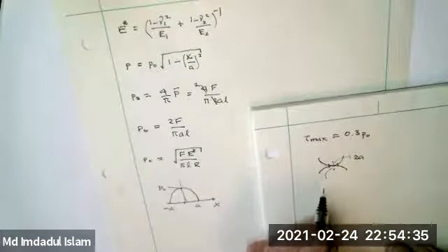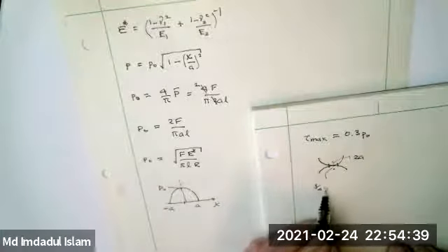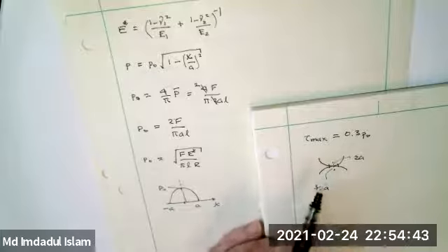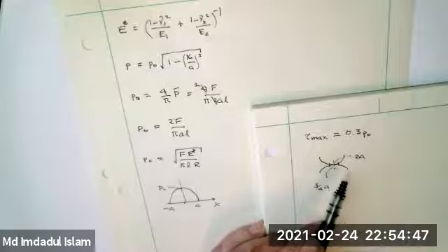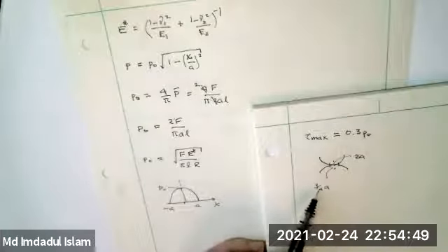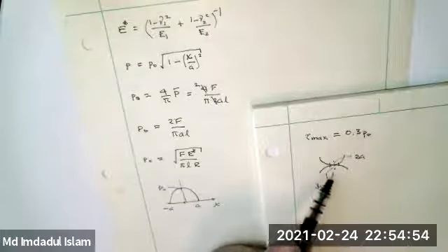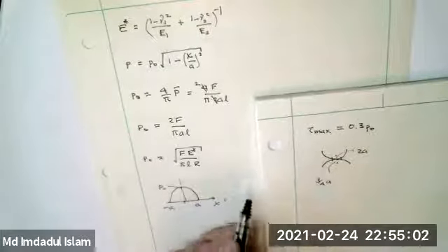This distance here is 3/4 of A. It's going to turn out with most of these metals, we'll do some examples, I think I did one last time, that this A is in thousandths of an inch. So 3/4 of an A is not very far below the surface, but it's subsurface. One of the things that means is damage occurs below the surface and you don't see it until the piece pops out and the thing is already damaged. That's the standard failure.